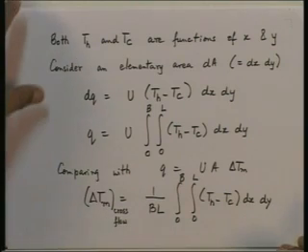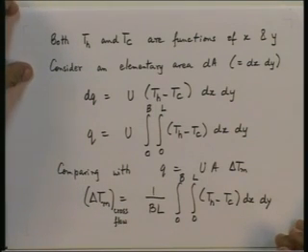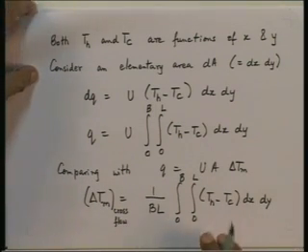So, you can see it is more complicated than we had earlier. We have now got a double integral which has to be handled. So, the determination of delta T m is going to be much more complicated. It has been done numerically. So, we do not have to worry about it, we will get the results, but it is not as straightforward as it is for parallel flow or for counter flow, which were one dimensional problems.